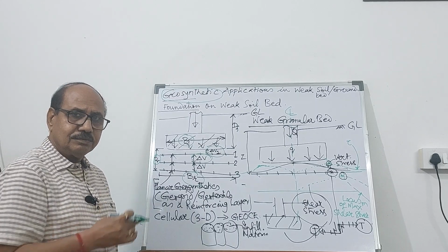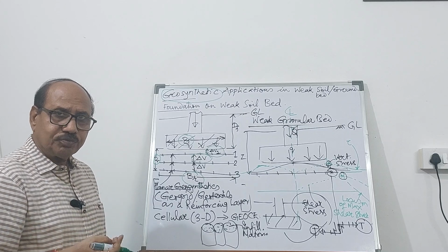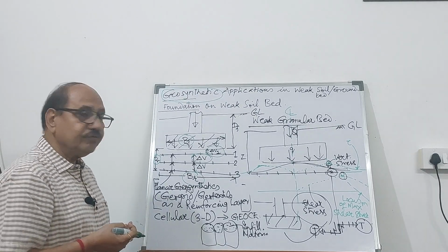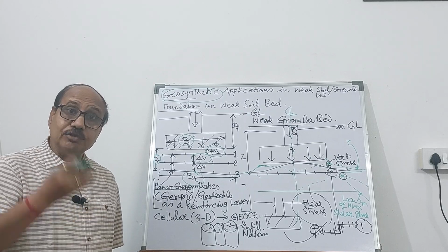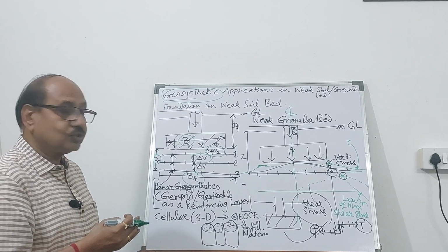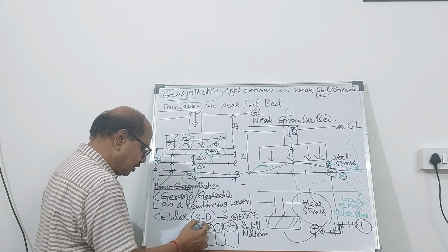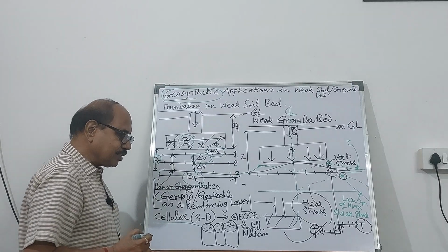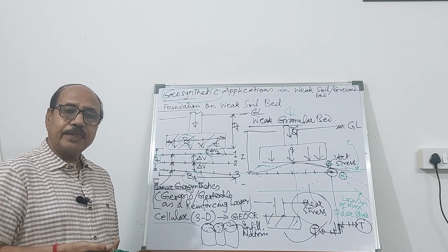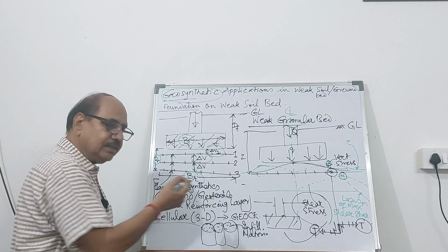I have done it, and I found that the bearing capacity improves by 300% in weak granular deposit. Even in weak cohesive ground, soft soil, geocell, a three-dimensional cellular geosynthetic material, works wonders because of the confining effect.